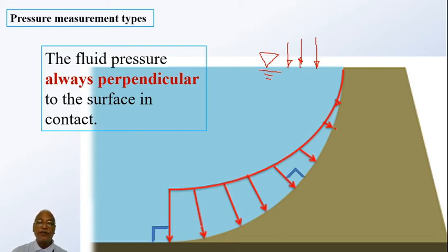Every arrow over here is perpendicular to the surface. You can just see here, this is 90 degrees, this is 90 degrees, this is 90 degrees. So everywhere it is 90 degrees. So the pressure always acts perpendicular to the surface. This is a curved surface. It's a good example of how the pressure continuously changes its direction and acts perpendicular to the surface. No component of this pressure will be trying to push the liquid down the line. Because of that, there is nothing like sliding, right?